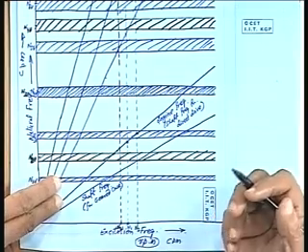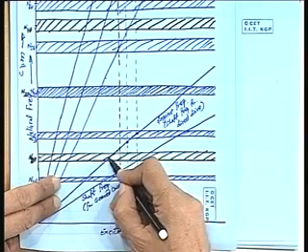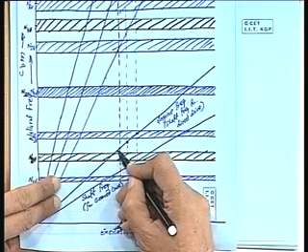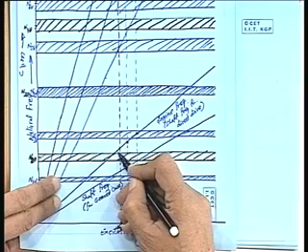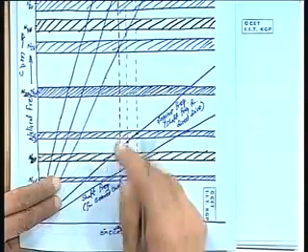What is the loss of power, and for that loss of power what will be the drop in the RPM. So you have to travel along with this, whether it still comes under this band or it is still clear of the band. If for that lifetime, considering the drop in power and the corresponding drop in the RPM, it is still clear of any frequency band, accept it.